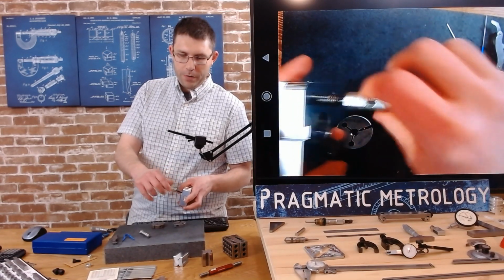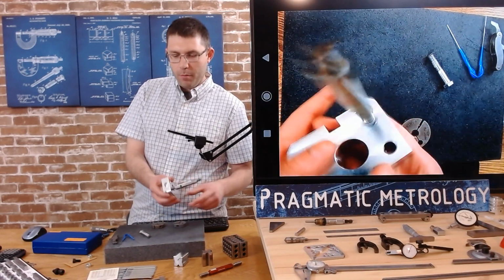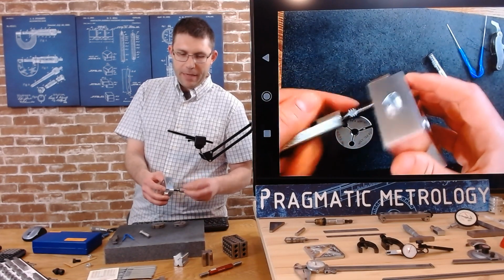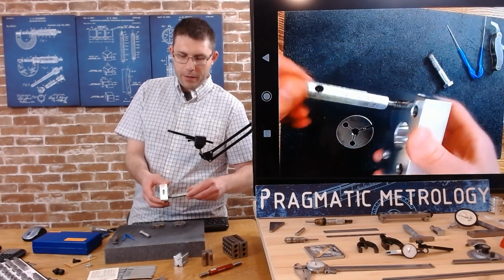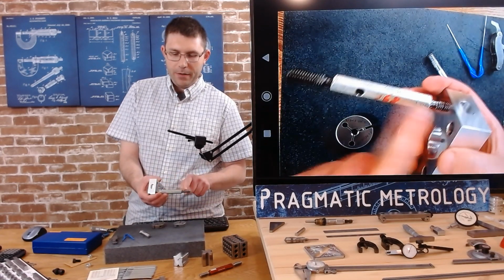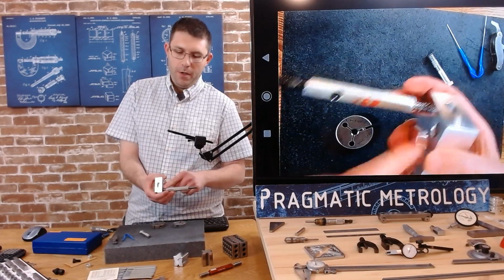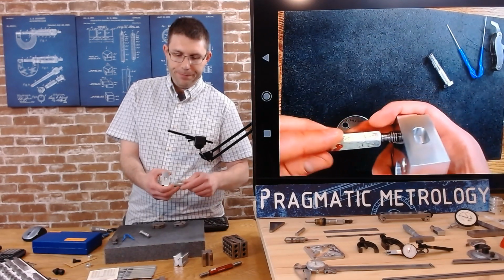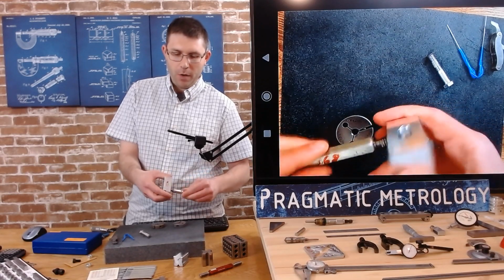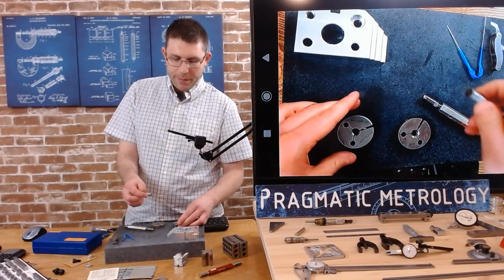I'll put my Go into this 3/8 16 hole on the angle block, and it goes just fine. And then I'm going to take my NoGo and try to thread it in, and it locks right away. I can't do it. So these gauges are designed with different pitch diameters. The Go pitch diameter should go in the hole, and the NoGo pitch diameter should not. So can't even really force it. I definitely don't want to try to force it. You'll damage your thread and you'll damage your gauge.